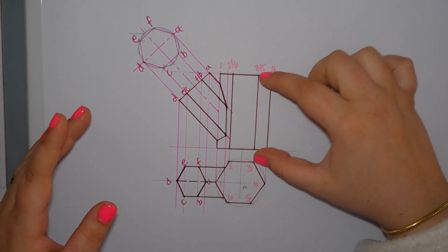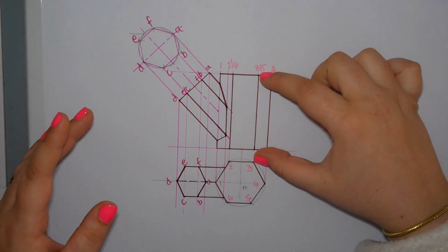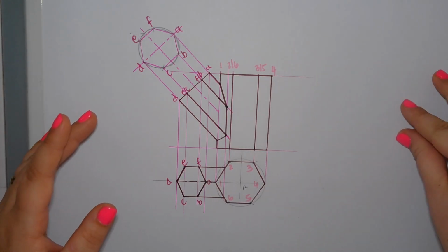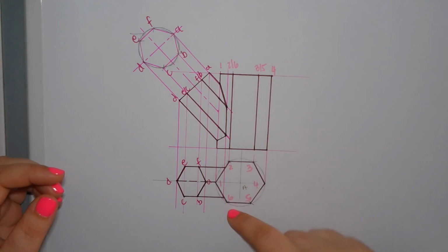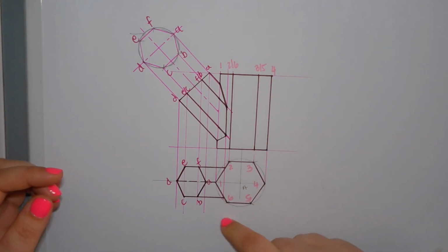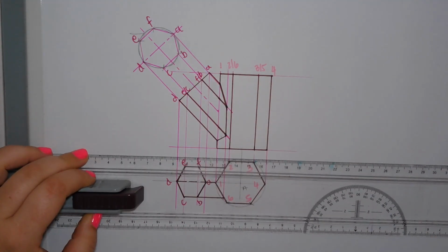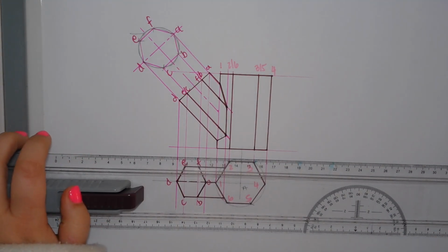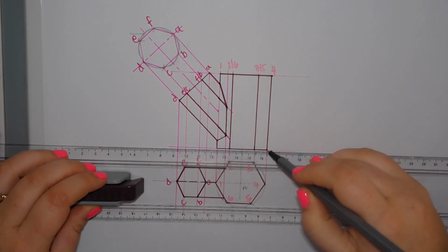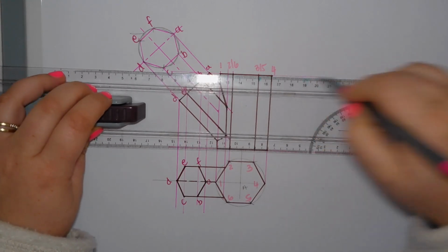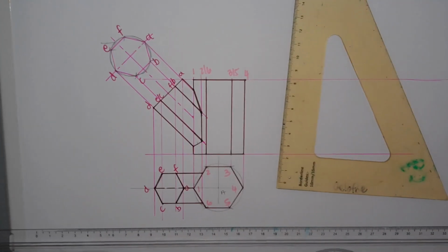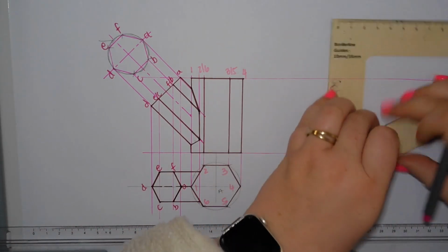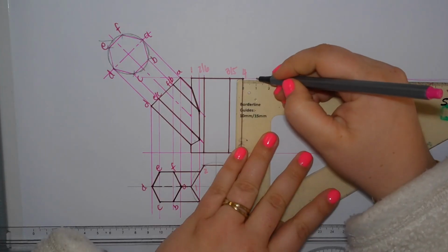So main pipe is this hexagon over here. And because I have space over here, I'm just going to extend the height over. So remember with the previous sketch, we took the height down to a spot where I had space. So I don't need to do that. I'm just going to project it to the right of the page. And I'm going to give myself a starting point. So it can be, if you want to, 10 millimeters away from your sketch.